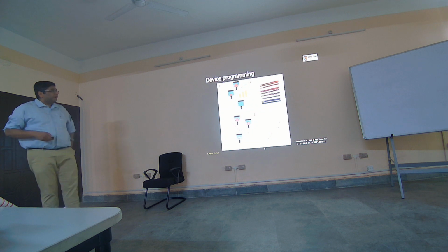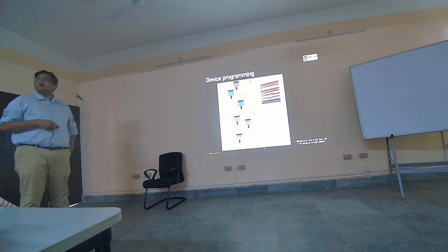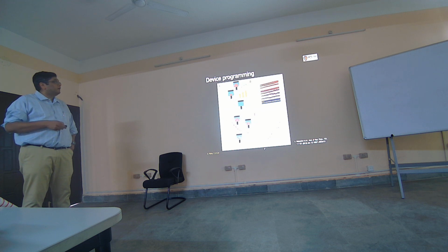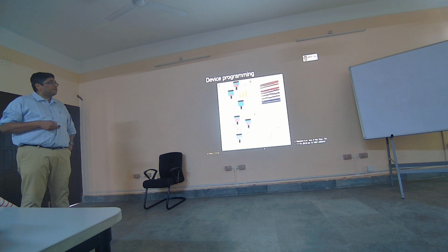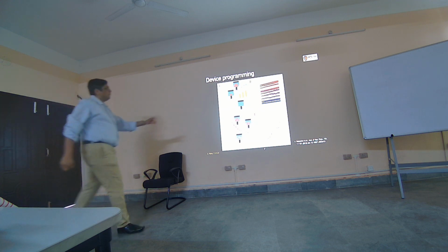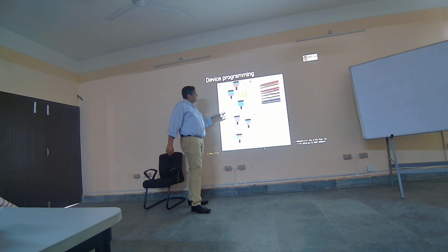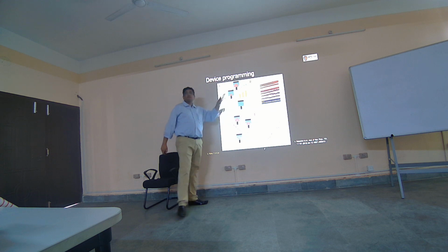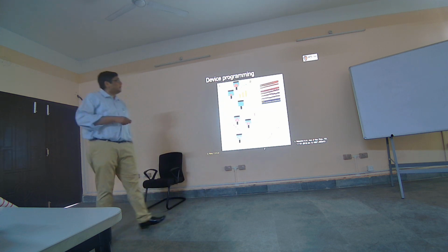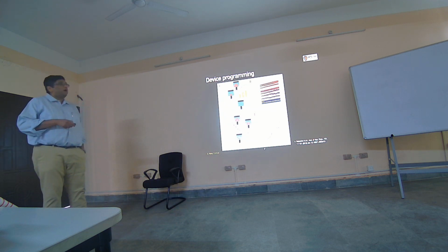So here is some data. Again, a lot of this work is similarly done from IBM. You see that here is the programming current, and this is the resistance. By changing the programming current, you can get a large change, from roughly 2e4 to around 1e7. So you're able to get a large change in resistance by playing around with the amount of amorphous to